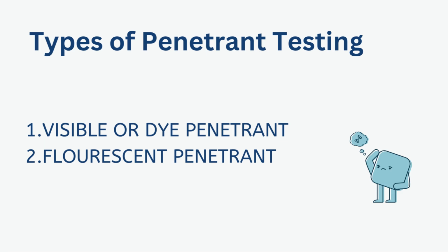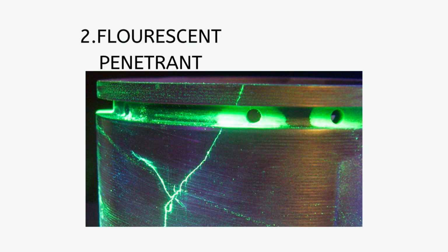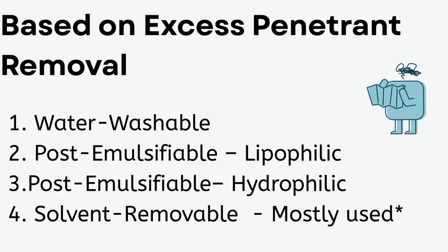There are two major types of penetrant testing. One is visible or dye contrast penetrant testing, another one is fluorescent penetrant testing. Further, based on excess penetrant removal, penetrant testing is classified into 4 types.